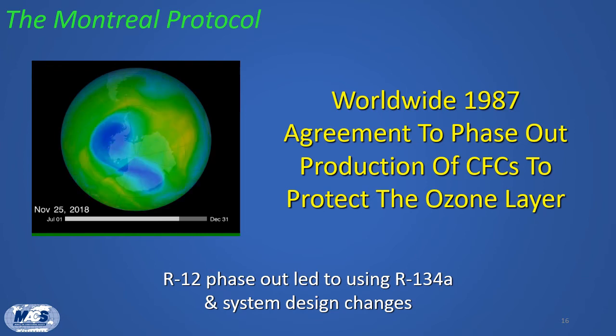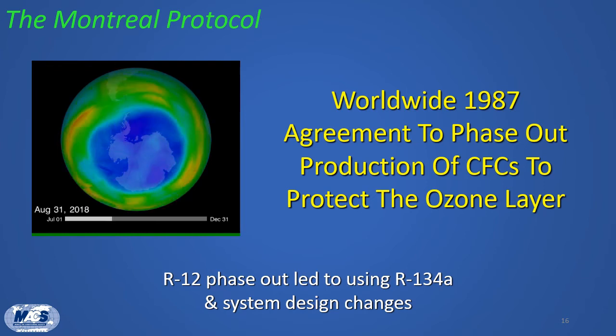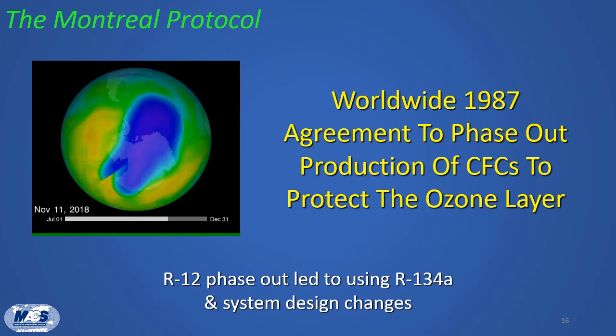The most notable change, however, is increased condenser capacity and increased airflow to reduce system pressures at low-speed operation and city traffic conditions. In general, condenser performance for R134A systems increased approximately 30%. However, current environmental concerns are bringing about a switch to the use of more climate-friendly refrigerants due to global warming and climate change.